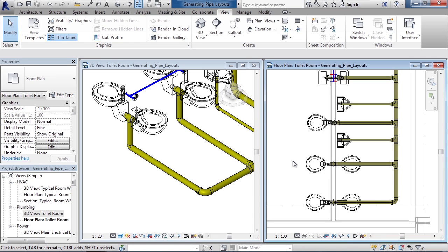We also talked about looking at multiple windows, tiling these views so you can look at two different views of the same thing at once. We routed pipes from an existing fitting by right-clicking on the drag handle and then choosing Add Pipe. And we also looked at the pipe routing settings, where we could control what type of Ts, what type of elbows, and what type of pipes are actually being applied to our pipe system as we route our pipes.